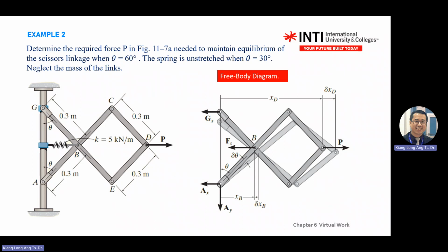A is pinned to the ground, so you have two reaction forces there. At this point, it doesn't matter. For example, at A, it doesn't matter whether it points to the left or right, but it's highly recommended you fix to one direction you prefer, so that you know how to solve. So this one is just pointing out. It's just spreading out all the forces.